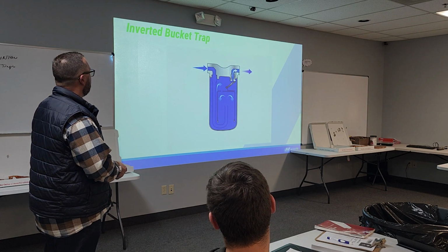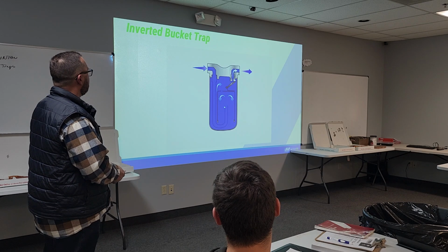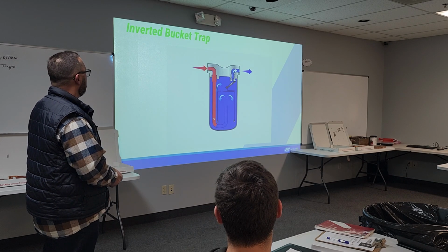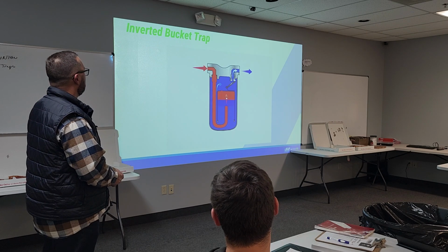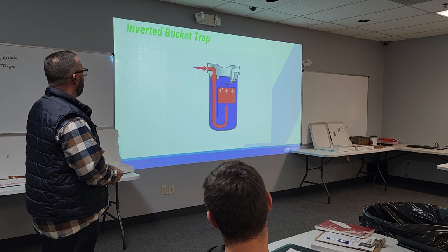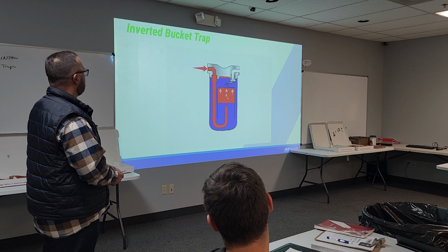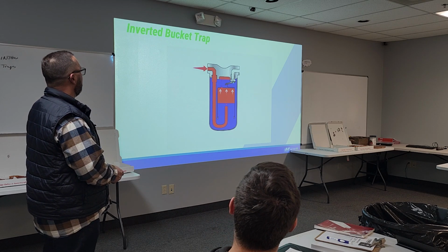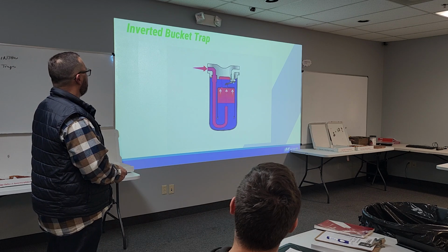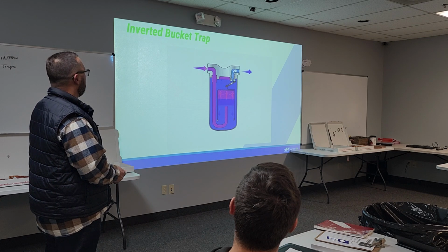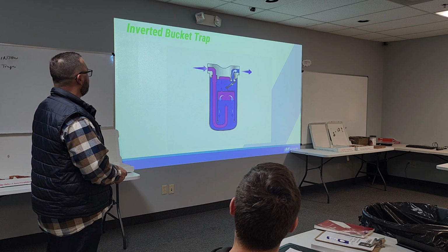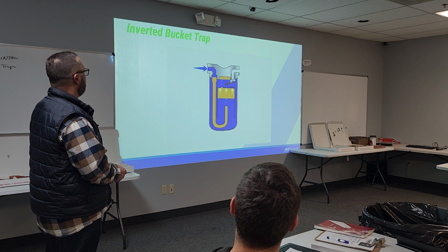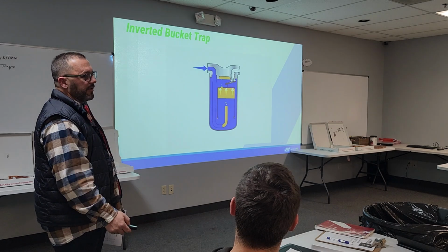So again, this is normally open. This is under cold condition here, and as live steam comes up, it will start to bleed the air through that little hole, live steam holding that guy up, keeping that head and seat closed. Then as soon as you make that phase conversion back to condensate, that's where that bucket falls, becomes non-buoyant, and lets all the condensate pass. Very simple.